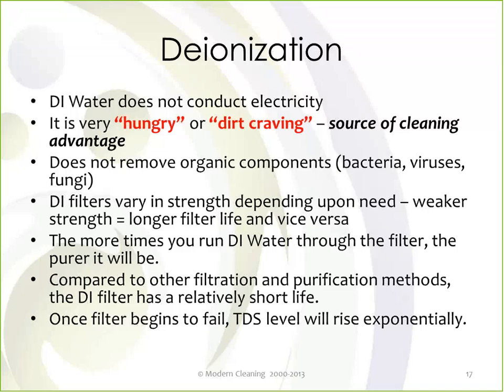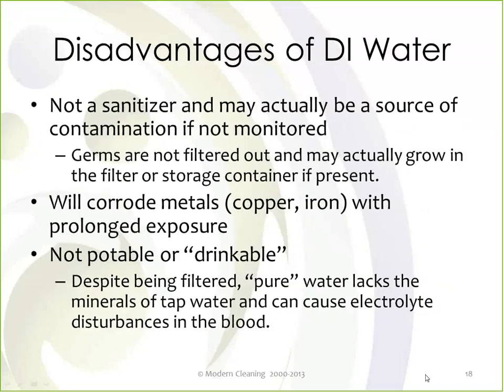And in more scientific environments, they can run the water through the DI filter more than once to get it even more pure. And once a filter begins to fail, as Tom mentioned, the TDS levels rise exponentially. That's why it's important to test your water.